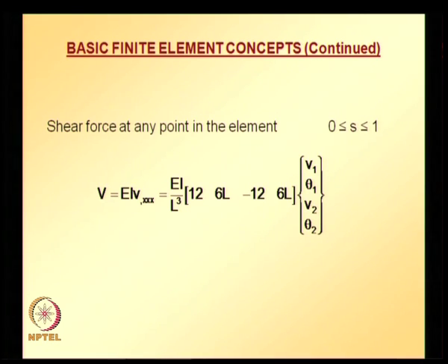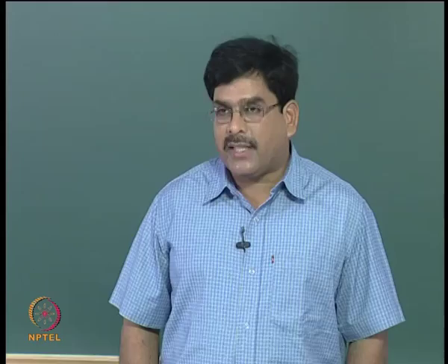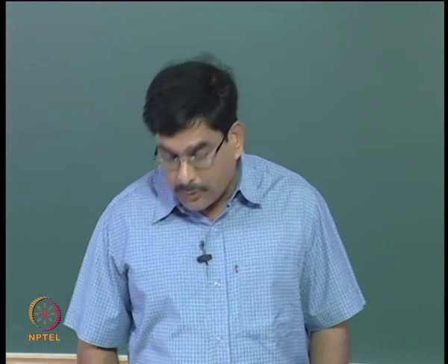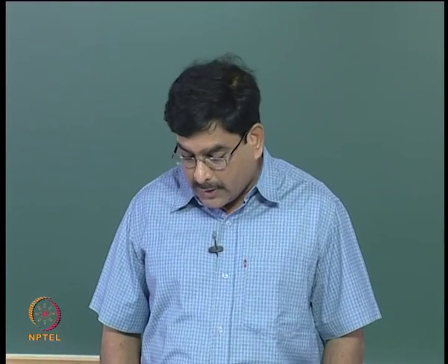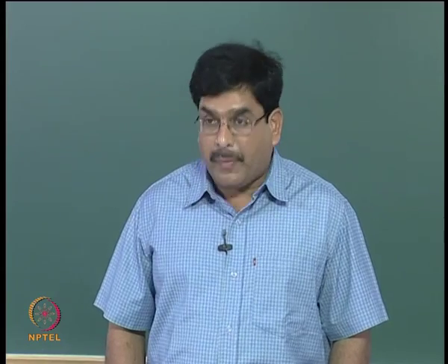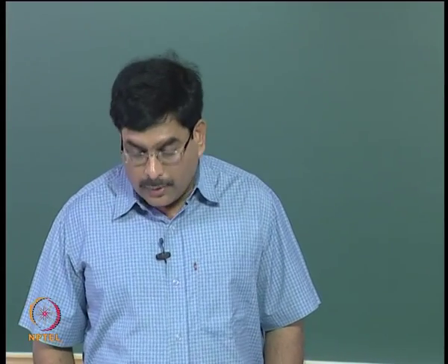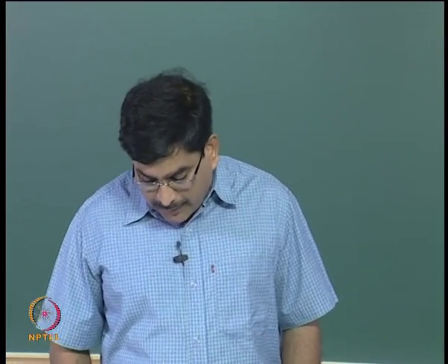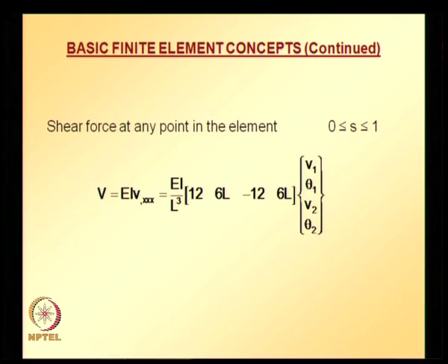What if the beam is not prismatic, that is, non-uniform beams? This particular element may not give the exact solution. In that case we have to use more elements per span for better accuracy. Also, if we have distributed loads, the solution may not be accurate and we may need to use a special technique called the superposition technique.